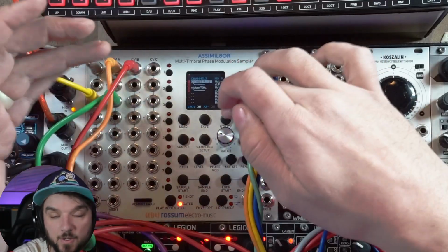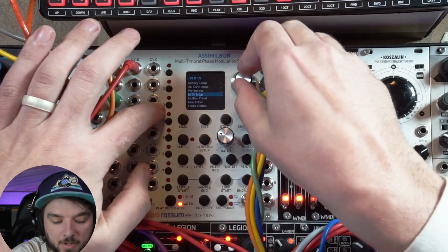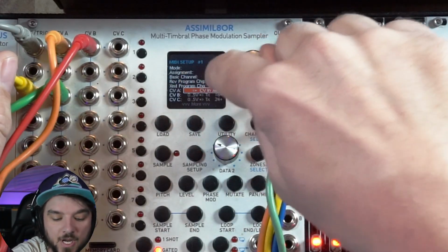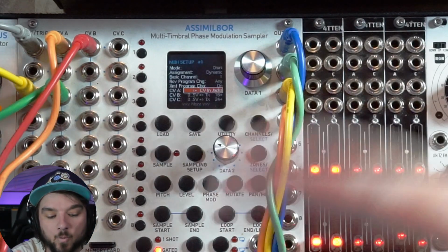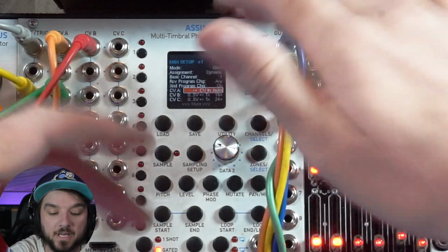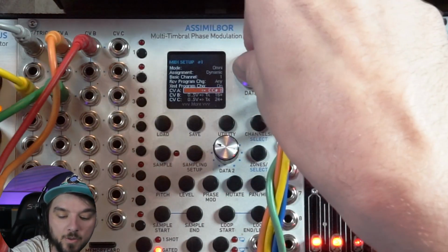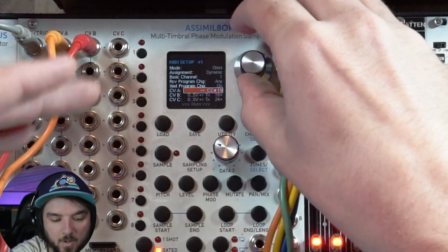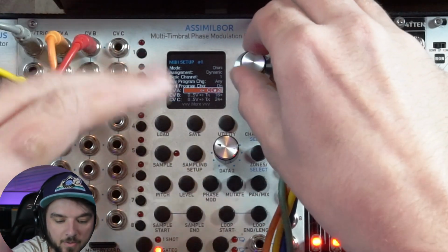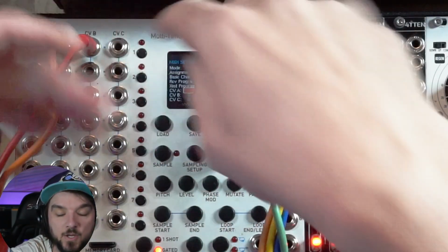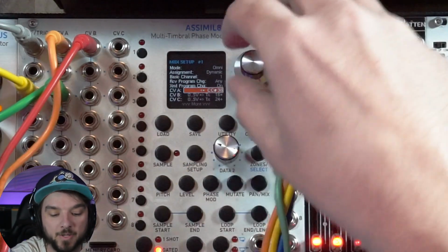So all we have to do to set up the MIDI output is go into MIDI Setup. So normally what you see when you go into this is CV in jacks with an arrow going to the left. And what this means is that it's just expecting CV on the jacks, and that's going to control things inside of the Assimil8or. When we go to the right, you start seeing CC numbers. And this is basically the CC number that you're going to replace that CV input with. So CVA you can replace with an incoming CC.